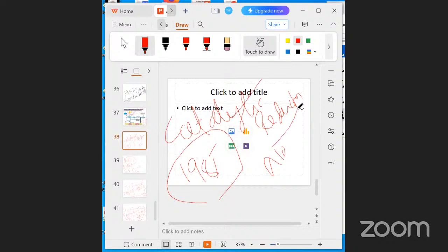The nitrogen is not in the actual fuels used in motor vehicles or power stations. It is introduced from the air when combustion occurs. So using less air in combustion can reduce emissions of nitrogen oxides. Temperature also has an effect on emissions: the lower the temperature of combustion, the lower the production of nitrogen oxides.